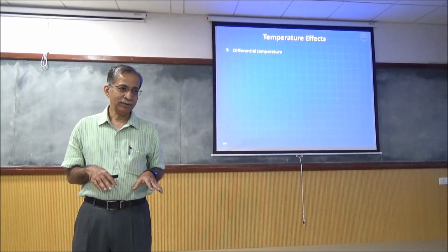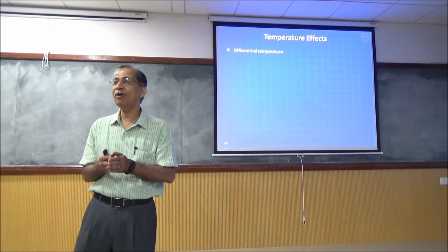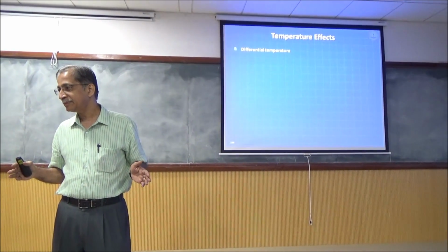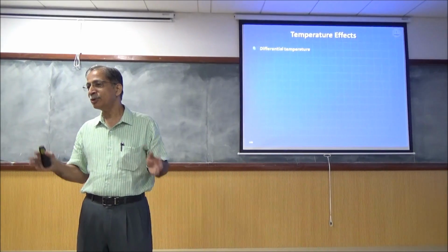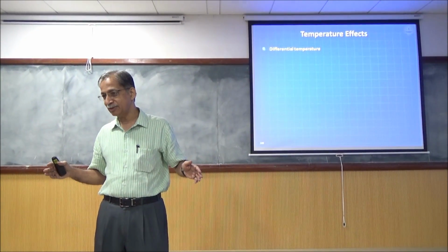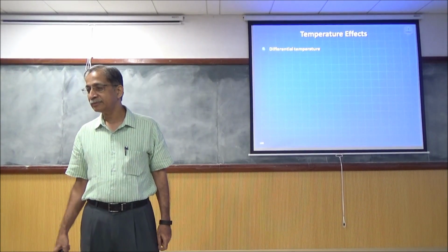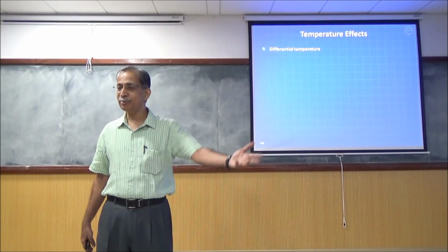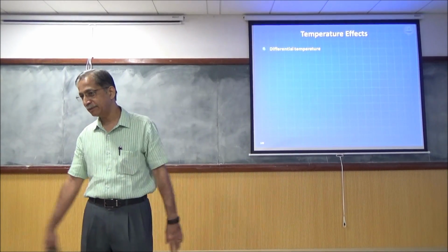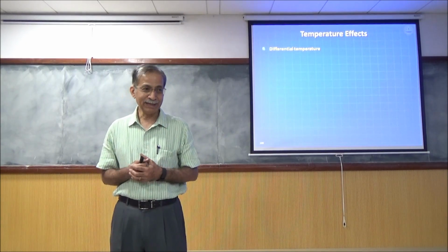In the Indian code, the recommendation is if the length in any direction exceeds 45 meters, what should you do? It's desirable to provide an expansion joint. If you don't provide an expansion joint, you should do a thermal analysis and put additional reinforcement wherever required. The problem is many people don't know how to do thermal analysis.